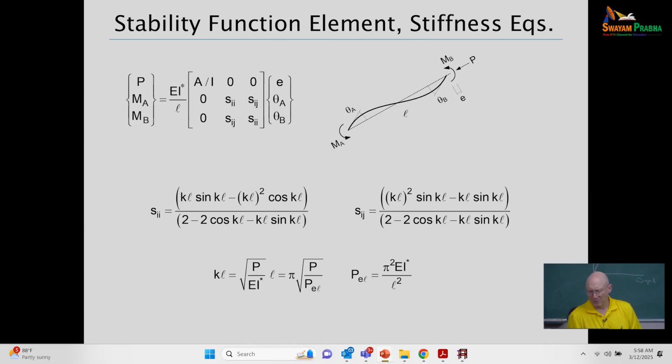And if we have the two moments here, I'm not showing shears. I'm just tracking how the moments relate to the rotations theta A and theta B relative to the chord. Clearly, if I have moments MA and MB here and no transverse load inside the element, I can get a shear force. MA plus MB over L is my shear, and then equal and opposite to that at the other end. That's all we do to get from the 3x3 to the 6x6, or one part of it.